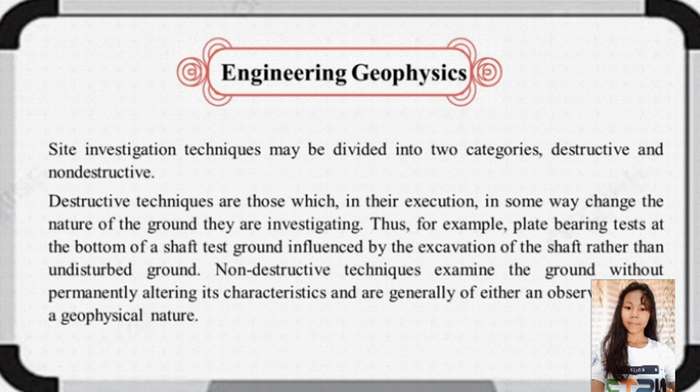Geophysical techniques fall into two main streams. In the first, naturally occurring phenomena such as gravity, the Earth's magnetism or telluric currents are measured with great accuracy for values anomalous within general trends or reflecting local geological conditions. In the second, active methods in which some form of signal is passed into the ground and changes or responses to this signal resulting from geological conditions are observed. Seismic and geoelectric techniques are best known of this group.